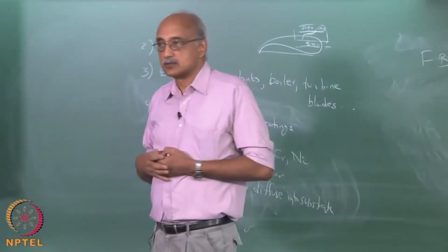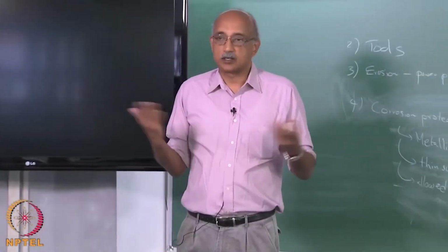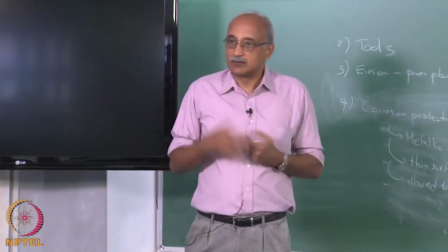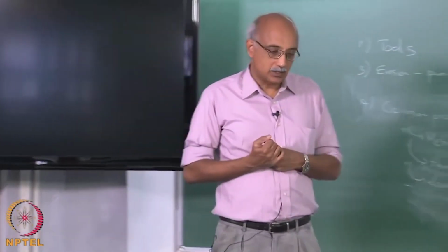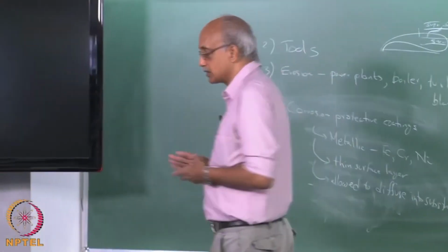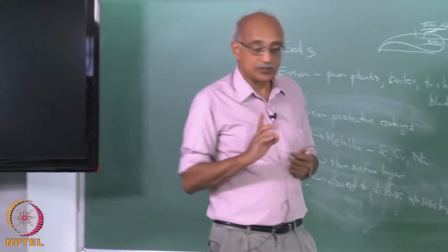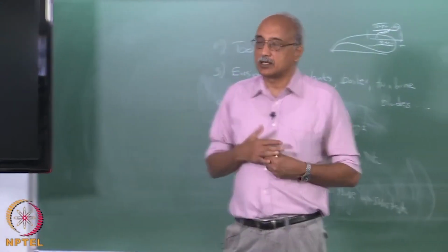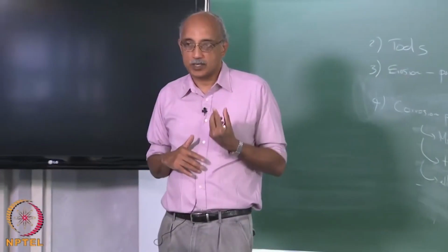So, that is one example, but the plastics are used in many demanding environments because of their lightweight characteristics. So, anytime you talk about propulsion, payload, space applications, rocket launch, if they could, they would make the entire rocket out of plastic, right, because it's the weight of the rocket is what you are constantly fighting when you are launching. So, plastics are a highly desirable material, and rubbers also. So, all classes of polymers are very desirable in terms of certain properties, but they do have this one issue that a plastic surface can easily wear. It can easily be abraded, can easily be eroded, cannot be corroded so much, but physical damage is quite possible.